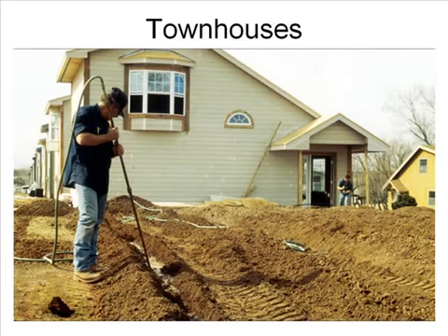A number of townhouses have been done, and this is a retrofit of a townhouse that has air source equipment on it, and so the building owner in this particular case has decided that it's to his economic advantage every time one of these things needs to be replaced, the air source equipment, to replace it with the ground source. In this particular case, the person here on the end of that lance is washing the soil back into the trench and making sure that there's good backfill, because in this particular case the heat exchanger was a Slinky, which I'll show in the next slide.